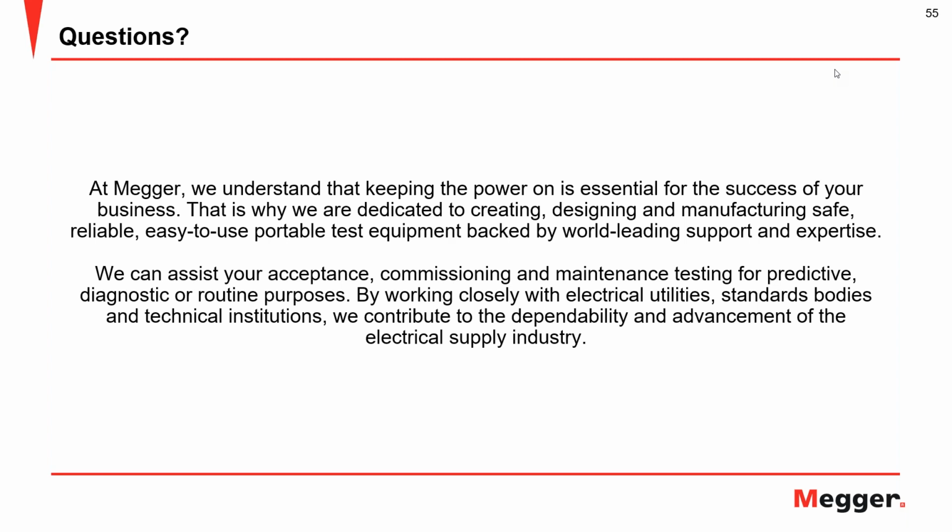So this is why it's a rule of thumb. It really depends on the cable that you're trying to test. So this is why it's so important to do a proper calibration, which you then save, and the software is using that calibration to determine the magnitude, the apparent charge of the PD event, and where it is to localize it. And your calibration will clarify all of these questions. If you put into the calibrator, let's say 1000 picocoulomb, that's a typical standard setting, and you see a good end reflection, well, then you will have no problem carrying out a very good test.